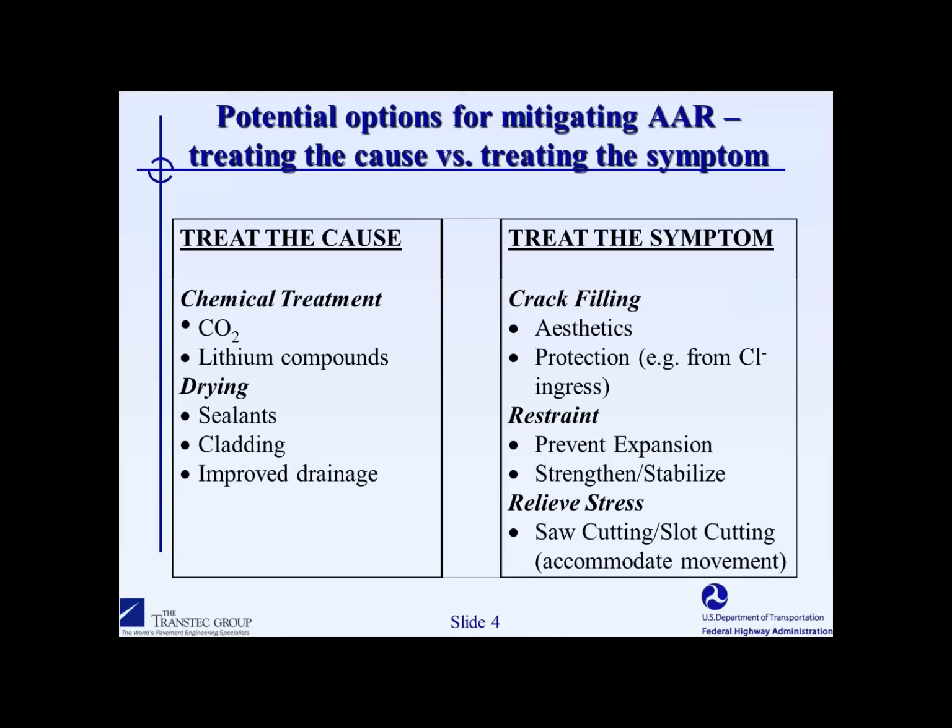What we will discuss more today will be the use of lithium compounds. And lithium has received quite a bit of interest in say, the last 10 or 15 years. And that's because previous laboratory work showed that if one could take small laboratory specimens and dry them out and then soak them in lithium nitrate solution to ensure a pretty high degree of saturation, that concrete would then expand much less than an untreated specimen.